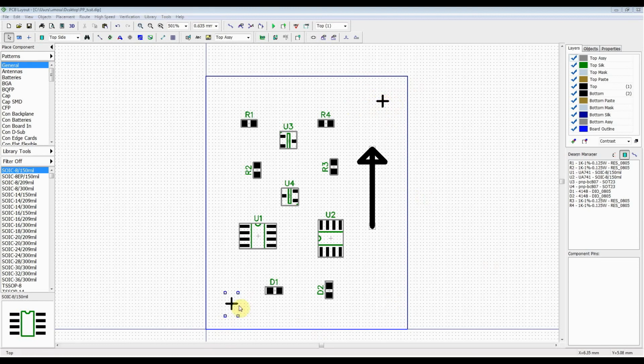I generally use crosses for that, since the fiducials on the MV10, when you're placing it, are a crosshair, so you can align the crosshairs to a cross centrally a lot easier than a little circle or dot or square. Single arrow just for me, to say that that's the top of the board, because I haven't really got any tracks coming down. I'll probably forget which way up that goes when we come to place it in the machine, so that's just for my reference.